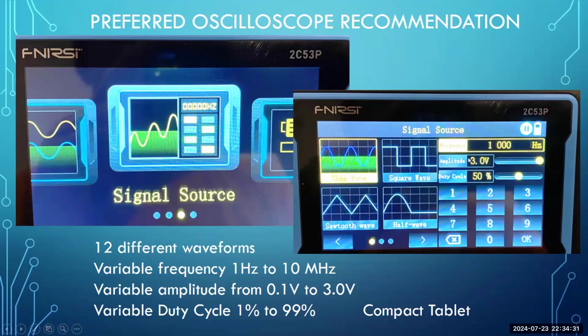It is a fixed 2.5 volt peak to peak waveform, and nothing you can do about changing its amplitude. If you want to change its amplitude to your circuitry, you will have to build additional voltage divider circuitry on your breadboard to achieve any kind of variability. Here, the adjustments are built in.